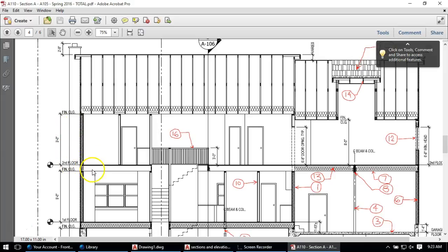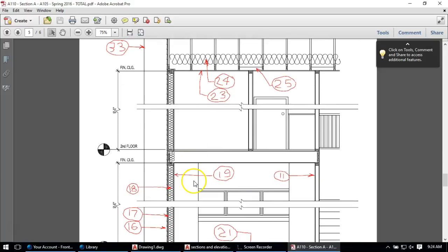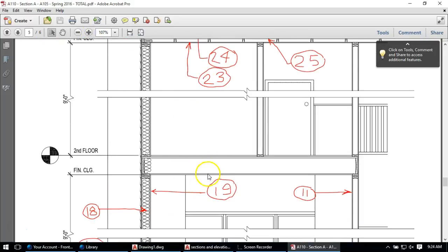And it doesn't give you this distance, so we're going to have to figure that out as we go. And we know that if we look up at our blow-up plan, the next image down, you can see that there's a piece of gypsum wallboard here, which is a 1/2 inch. That's what note 19 says. And then we've got this piece, which we don't know. It doesn't say. We'll actually have to go back to our structural framing plans we did previous week.